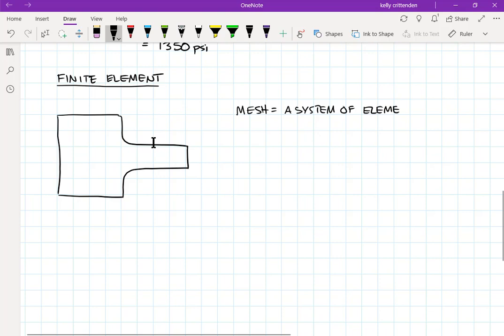If you know what you're doing, you can go in and manually create this mesh. Most things do not do that anymore. It's certainly not done on the first pass, when you're just trying to get your model to work. Most of the time you automatically generate this mesh. But when there are specific things or it's a really complex geometry, you may need to go in and specify some details about the mesh. What we're going to do is use a slider that says lots of elements or not lots of elements, and that's what we're going to do for our mesh customization.